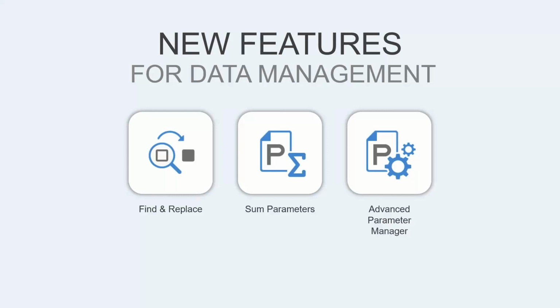So if a consultant gave me their linked model, did not give me a shared parameter file, I can now just search all of the parameters in the link and push them into my own model. And then also, if the shared parameter doesn't exist anywhere, we can use the UI to create it itself. And we can create those shared parameters in the project or push them directly into families. So another way to get parameters into families. So let's take a look at them.